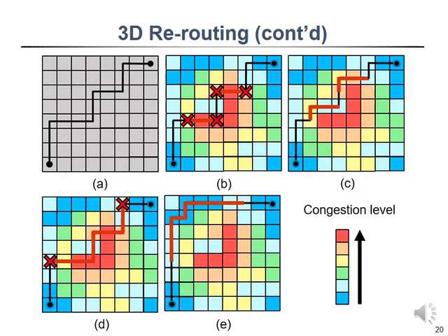The proposed concurrent layer assignment scheme has great ability to guide the 3D rerouting process, which is totally different from the conventional rip-up and rerouting after the DP-based approach. Figure A shows a net with 6 wire segments, and 2 segments pass through a congestion region with overflows, as illustrated in Figure B. As illustrated in Figure C, the rerouting of 2 separate segments may not effectively reduce overflow because it is very likely that their neighboring regions are still congested.